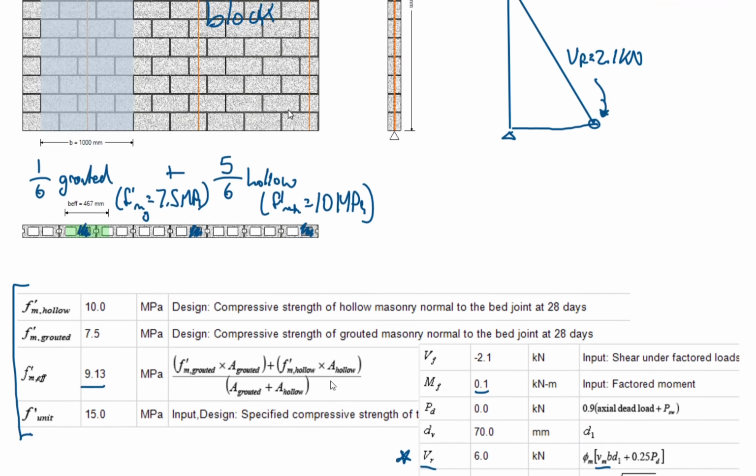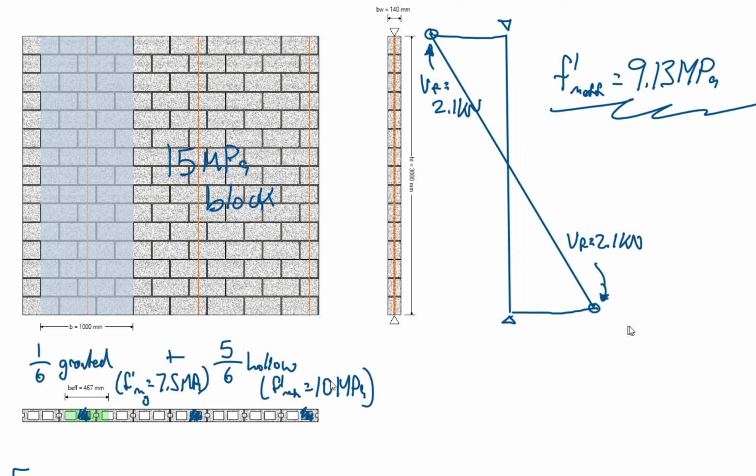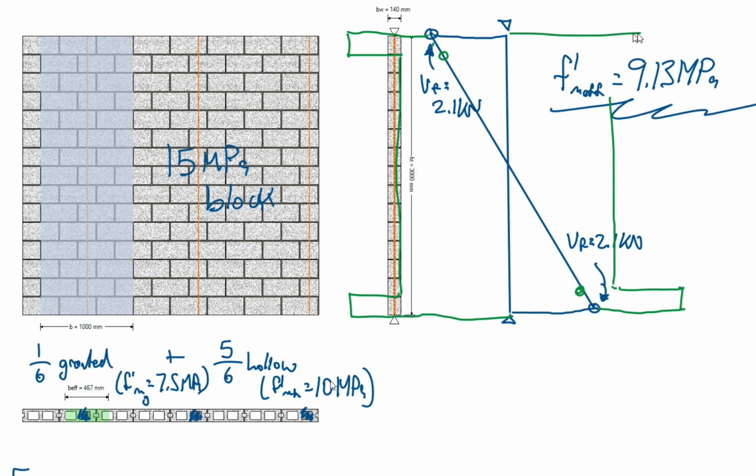The reason I'm pointing that out is because oftentimes our shear resistance, if we look at it right at the support, we'll get one value. In this case, we have a shear resistance that is way up here compared to the factored shear. But if we look one course down, it drops by quite a bit to the value that we get for the rest of the height. And the same thing happens on this side. So when we're away from those supports, we get a big bump by checking it right at the support, whereas the difference between this and this value here is a much smaller change. So what we're going to do in the software is change it to checking it along the height for diagonal shear. But in the meantime, consider yourself informed. This is basically what we're looking at.